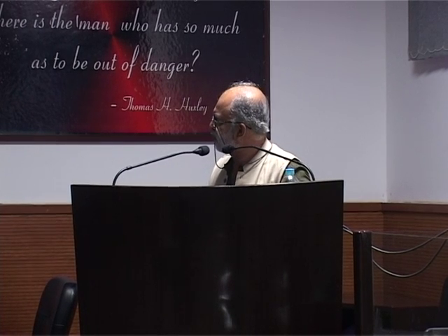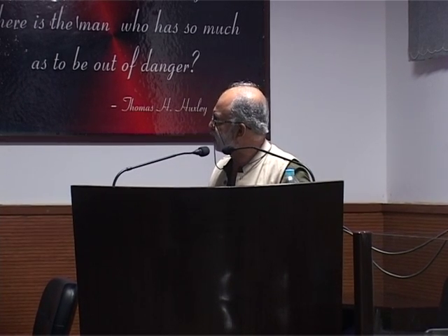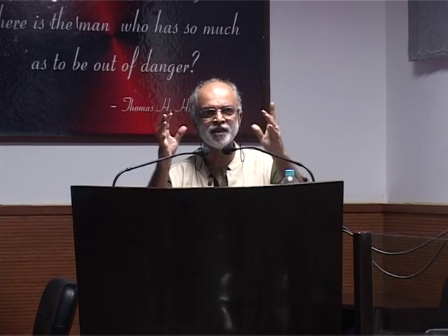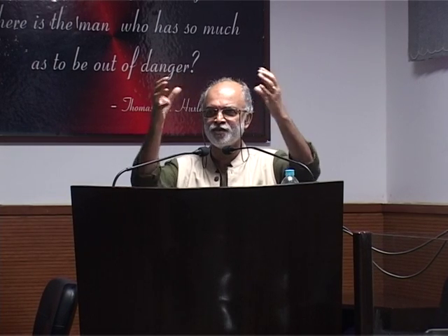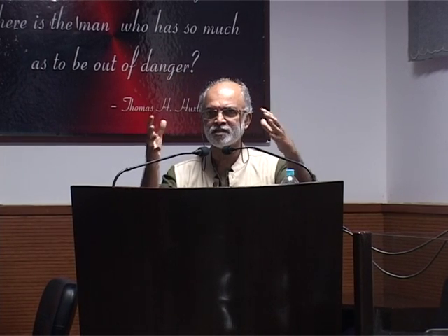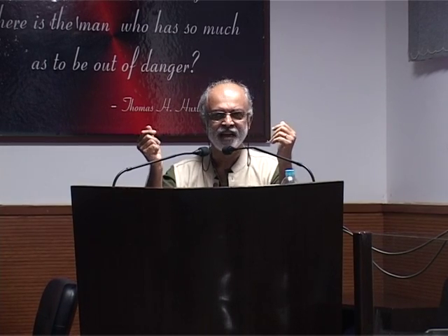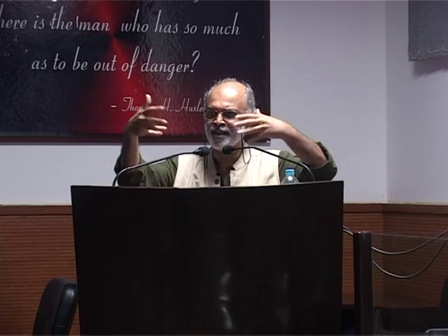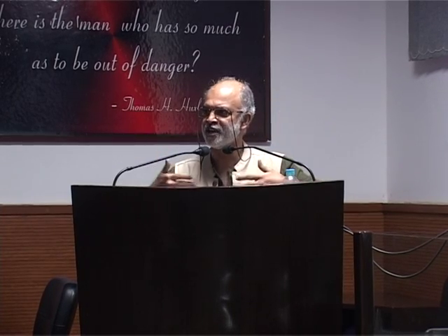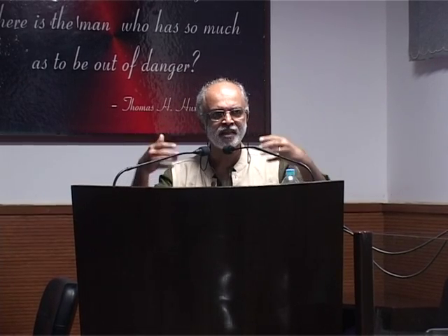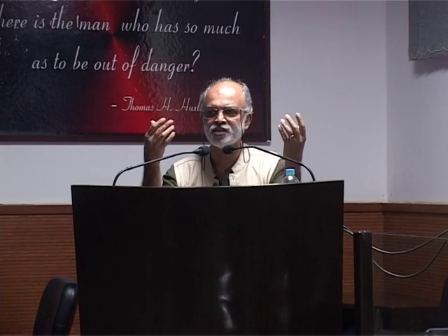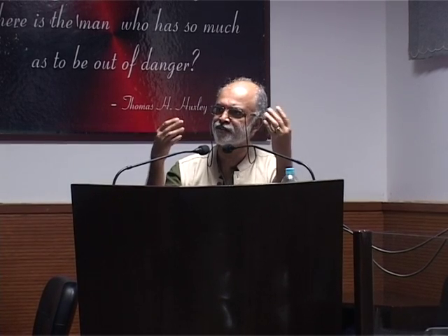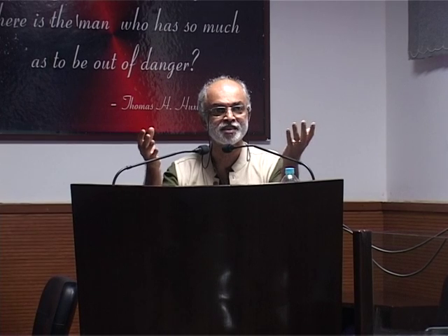When you have a solid surface, when the cavity size goes on reducing, the liquid will start rushing from all the directions to fill up that vacant space as a result of reduction in the volume of the cavity. Liquid is approximately 1000 times more dense than vapor, as a result of which a huge amount of momentum is associated with this onrushing liquid. Now this momentum will keep on compressing the cavity, and the cavity compresses at a velocity which is higher than the velocity of sound, which is 1500 meters per second.